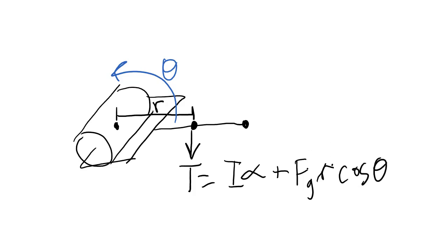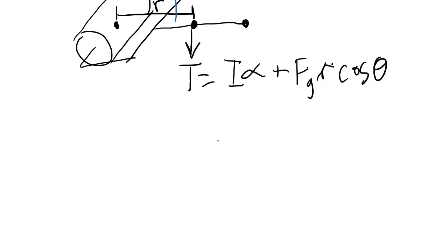Let's figure out how much more torque we would need in our motor if our manipulator was set up so that the motion was in this direction instead of in the direction shown in the last calculation. The force of gravity is the mass times the acceleration of gravity. And here I'll use L over 2 as the distance between the axis of rotation and the center of mass of the link.